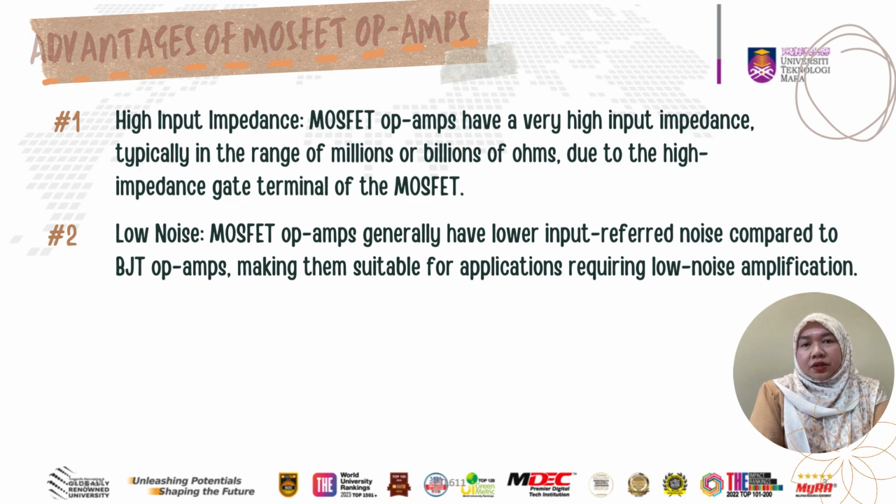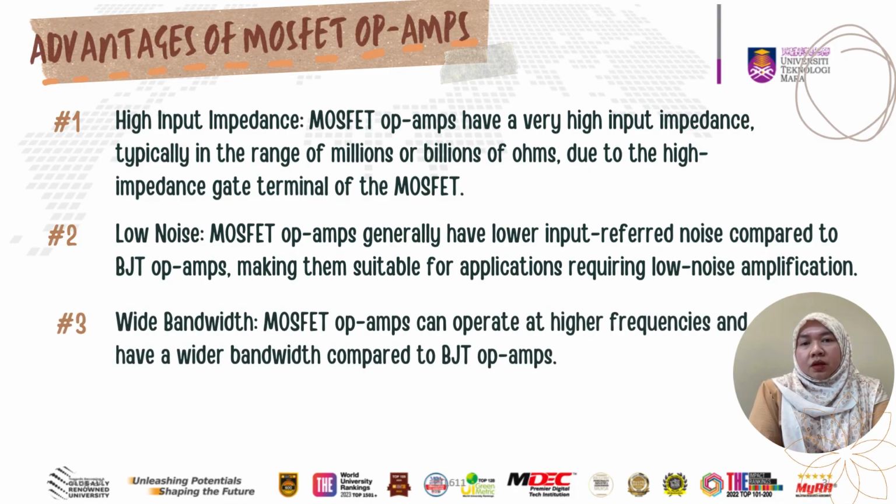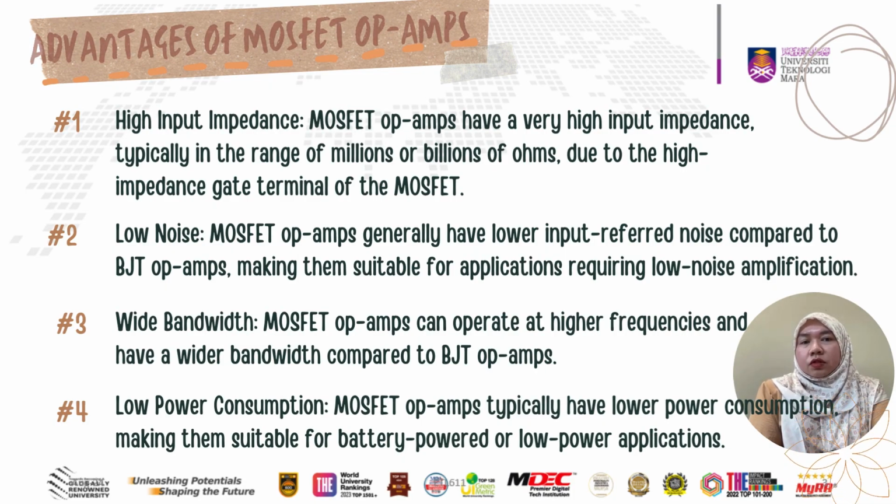Second one is low noise. It generally has lower input referred noise compared to BJT op amps, making them suitable for applications requiring low noise amplification. The third one is wide bandwidth. It can operate at higher frequencies and have a wider bandwidth compared to BJT op amps. The last one is low power consumption. It typically has lower power consumption, making them suitable for battery powered or low power applications.